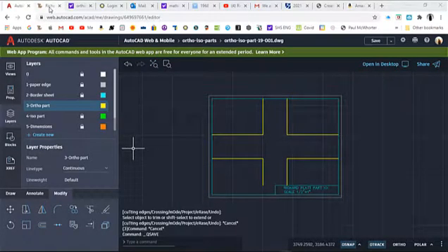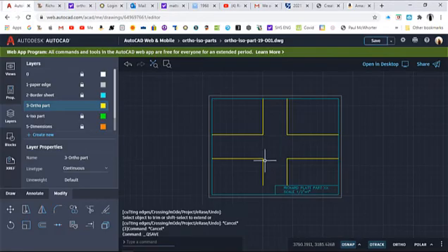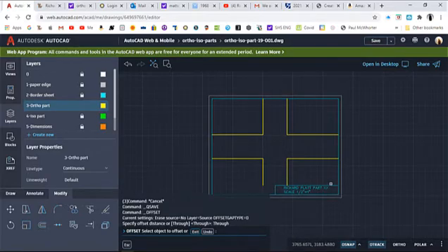Okay, the next step, we need to come back and look at the drawing. Okay, it says it's 4 inches across, so 4 divided by 2, or divided by half of that, is going to be 2 inches. So we're going to come over here, and at this time we'll go back to our good friend the offset command. We'll select that, and it says specify an offset distance.